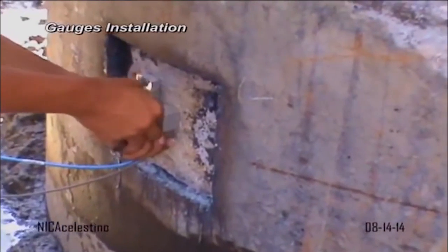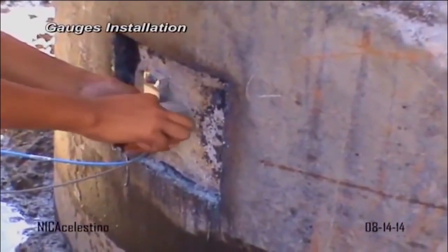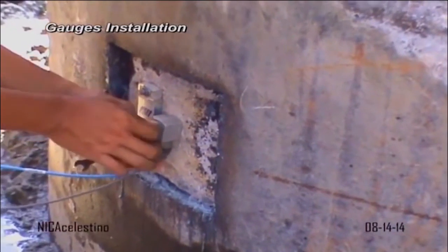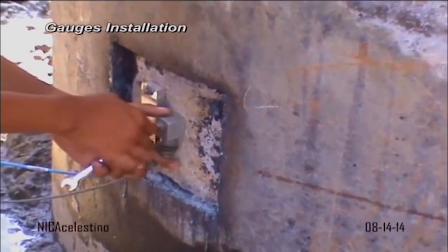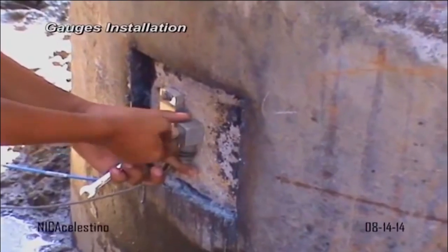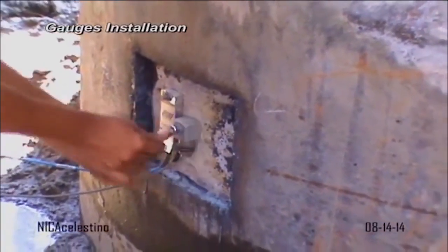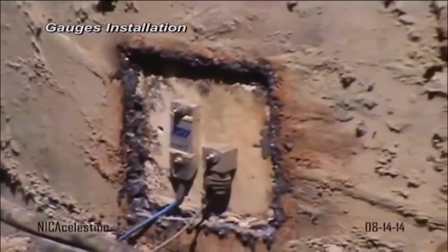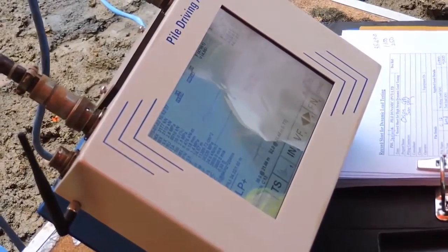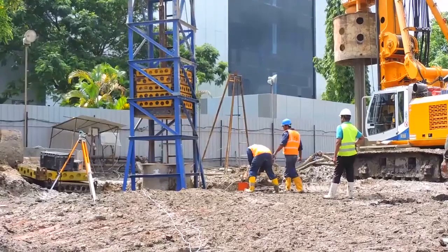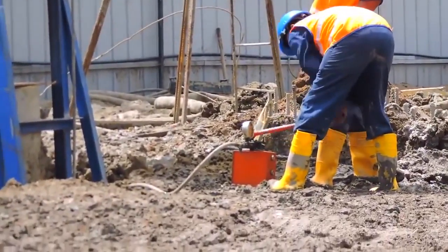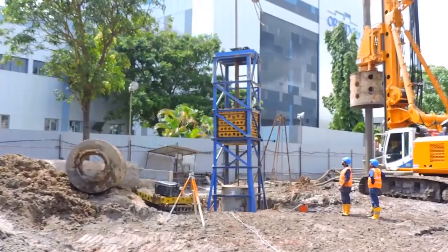Then the sensors of the analyzer are fixed to the pile. Then the load is lifted along the frame to the required heights and dropped onto the pile, giving a big impact. When the drop weight hits the surface of the pile, a big force is transferred by the drop weight and its velocity.